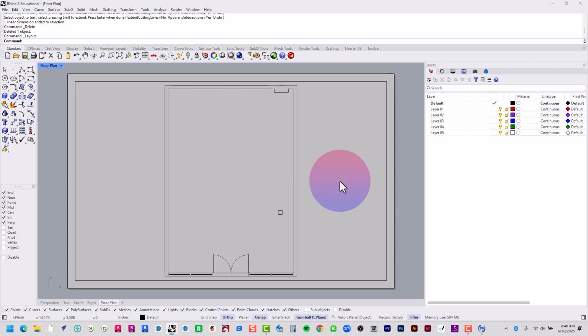If I look at my dimensions, it looks like 30 foot 2.5 is our longest dimension. So I need to figure out if I'm going to be using a 1/4 inch scale or a 1/2 inch scale. I might need to rotate this so it fits better on the paper. At 30 feet, if I'm using a 1/4 inch scale, how big is the 30 foot line?